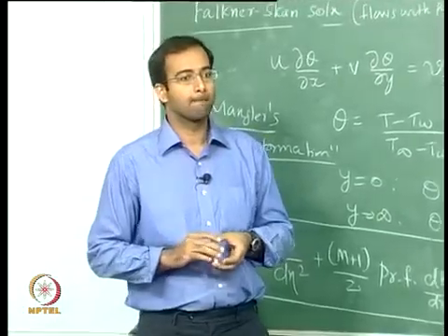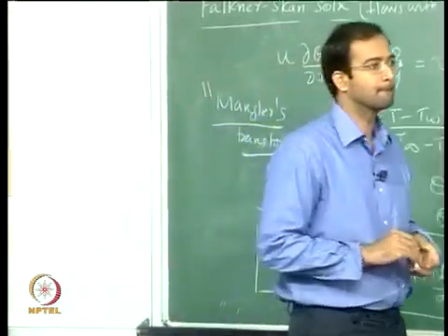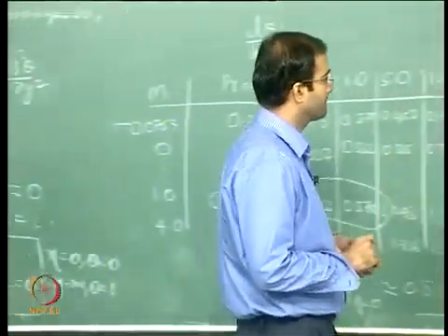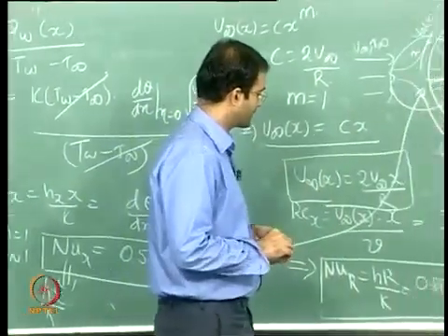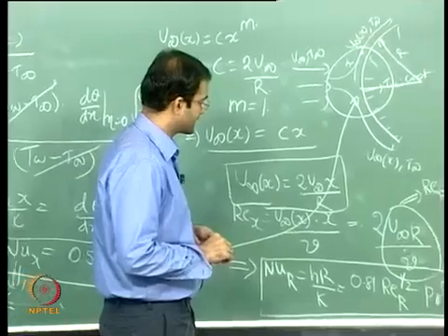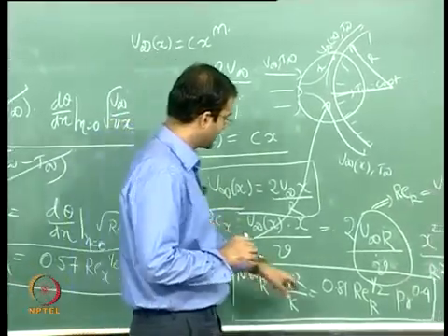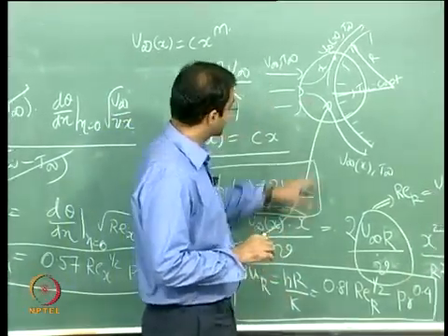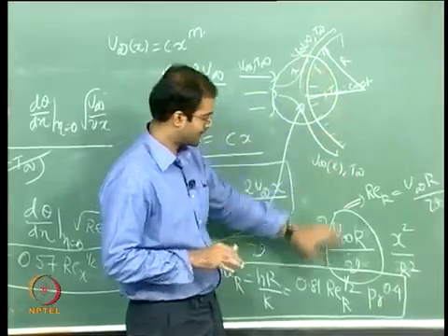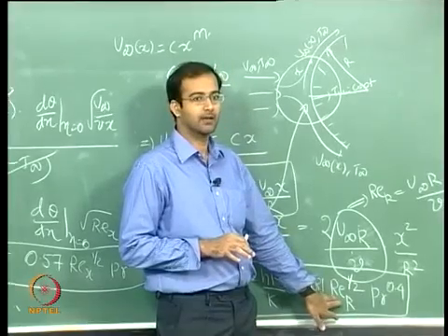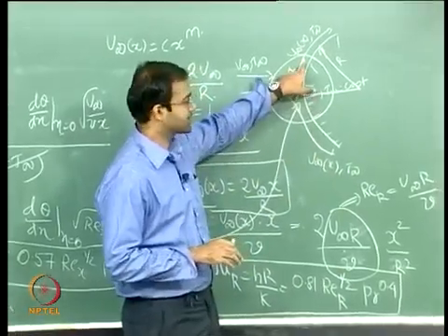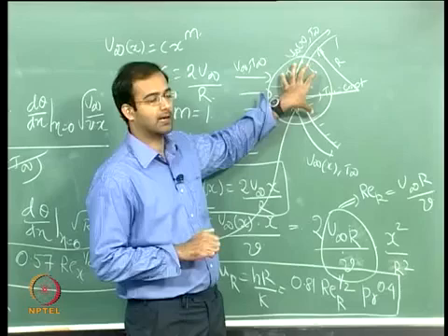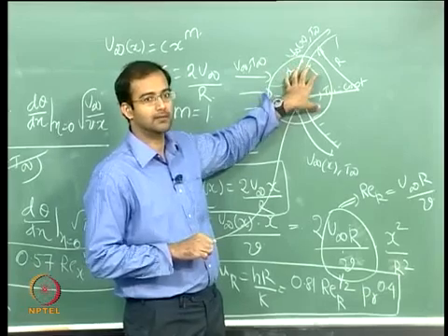So if you want to find out the transport at the stagnation point, how can we denote it? R is the same at theta equal to pi by 2. Yes. This only gives the Nusselt number in the stagnation region, that's it. You are not really varying x, because the variation in x is confined to a small region near the stagnation point.